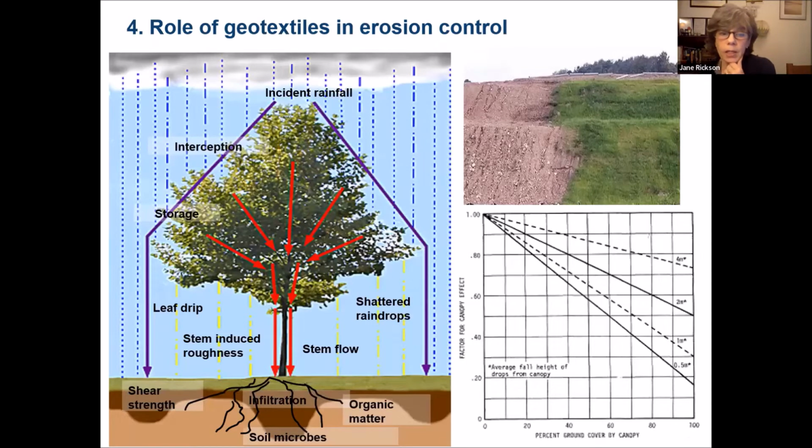A lot of my work uses this stuff, vegetation. Love vegetation. It's really, really effective at controlling soil erosion on sites. We know that vegetation is really good at intercepting any rainfall. It then stores a lot of that rainfall within the canopy of the vegetation. It breaks up the size of the drops into these shattered raindrops that have lower kinetic energy or erosivity to cause erosion. We've got lovely roots adding to infiltration. Fantastic stuff, brilliant. But it doesn't happen overnight.